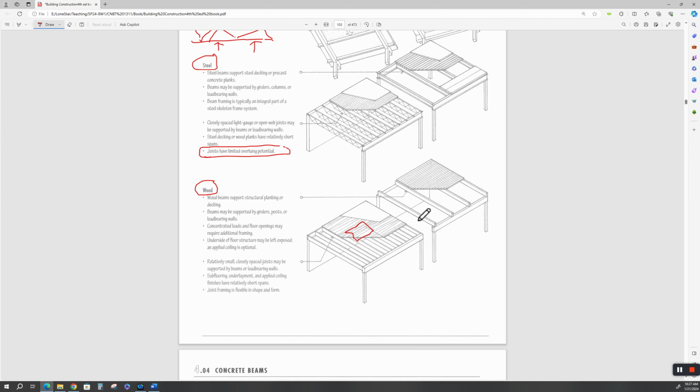But as you're laying your floor, your decking down, you've got to watch the deflection from the construction load, all those people up there and equipment and all that stuff. So you may have to do some kind of sub-jacking underneath until you get it all done, and then you yank the jacking out. All right, we'll see some examples of that a little bit.